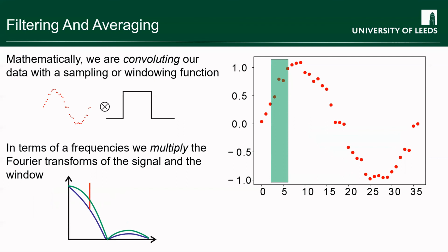So I've changed the frequencies in my signal by multiplying it by the Fourier transform of the filter. That's the effect of the filter: to suppress those high frequencies. The problem is that we're not really suppressing the frequencies quite ideally. What we'd like to do is simply keep the frequencies below some threshold and get rid of everything else above that threshold.